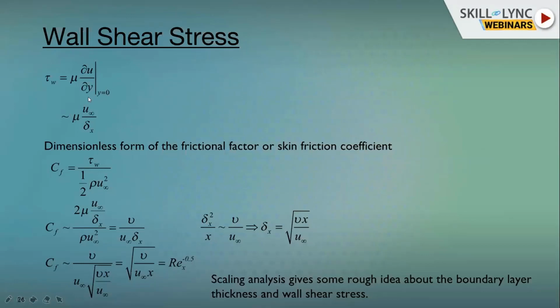because when you are developing the wall shear stress, the unit matters in which unit you are measuring. But this non-dimensional coefficient is unitless. They are the same irrespective of whatever the unit, SI unit or CGS unit, MKS unit, whatever unit you are following, right? CF equal to tau omega divided by half rho u infinity square.